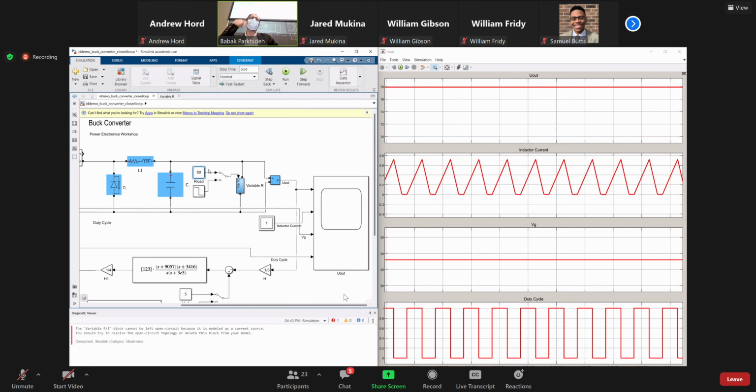That's an extra. The only reason that you would need that sort of impedance network is if you want to create a resonance, right? So you want to use the peak, like the previous, this fluorescent lamp. Some of them operate based on this resonance circuit. So actually they use a buck converter. It's very simple, exactly the same circuit, just assuming that this is like an H bridge or half bridge, and they put the midpoint on the DC side.